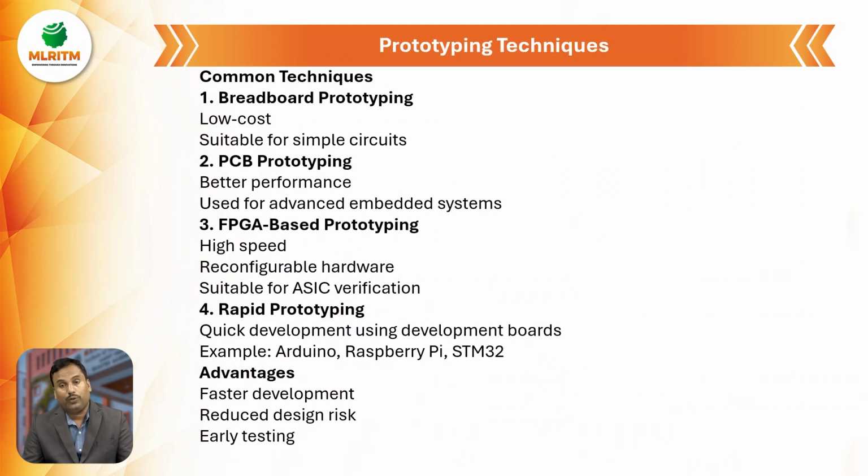So there are prototyping techniques. The common techniques include breadboard prototyping, because it is low cost and suitable for simple circuits. If you have the components, and you know the circuit and the application, then we can use the breadboard and interconnect all the components, then we can test our hardware.